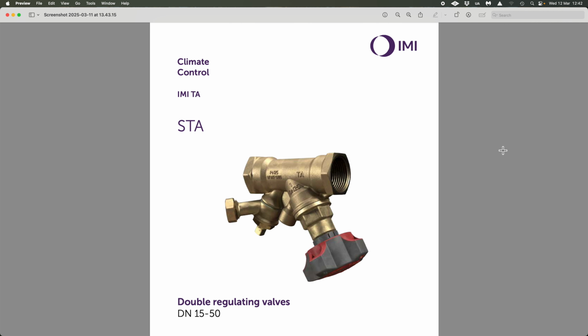Now, we talked about putting a pressure reducing valve on a system depending on what your incoming pressure is. And one thing that we have to remember in the UK, and certainly in the southern parts of the UK, is that most water suppliers will only guarantee 0.7 bar, so 7 metres of water pressure at ground level and at the entrance to your building. So this can be a problem, and we have some issues in much larger blocks of residential flats and things like that.